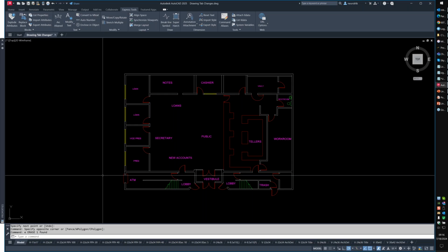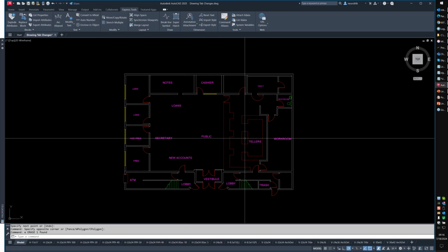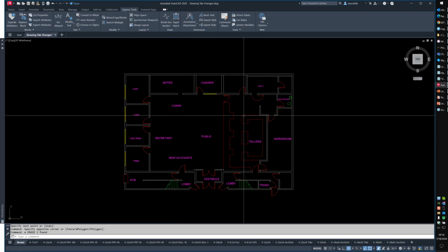So when people call in, they've had a crash or something like that, they can't find the SV$, that's usually what's happened. And again, if I trigger a crash event where it says, AutoCAD can't continue, we can save up to the last command, do you want to save the recover?